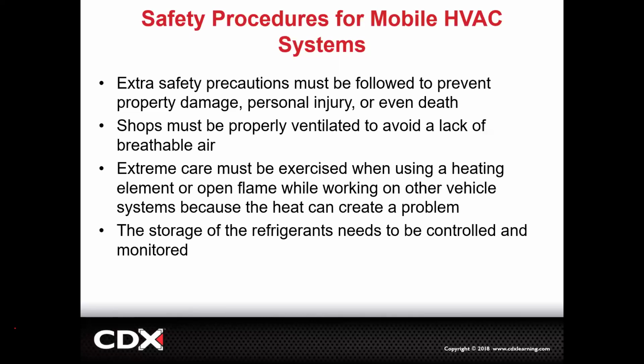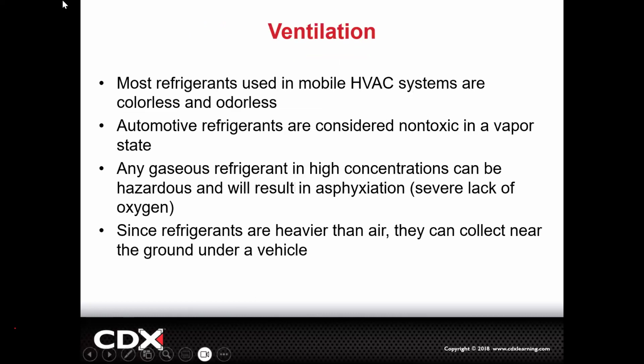Another thing to be worried about is ventilation. Part of the reason why is because, like what we see right here, if the refrigerant gets out, it's colorless, it's odorless, and yes, it's considered non-toxic, but if it's gaseous and it settles in the air, it displaces oxygen. It's heavier than the air, so it tends to lay low. If it displaces oxygen, what do you think this word means? Asphyxiation. It's like we can no longer breathe.